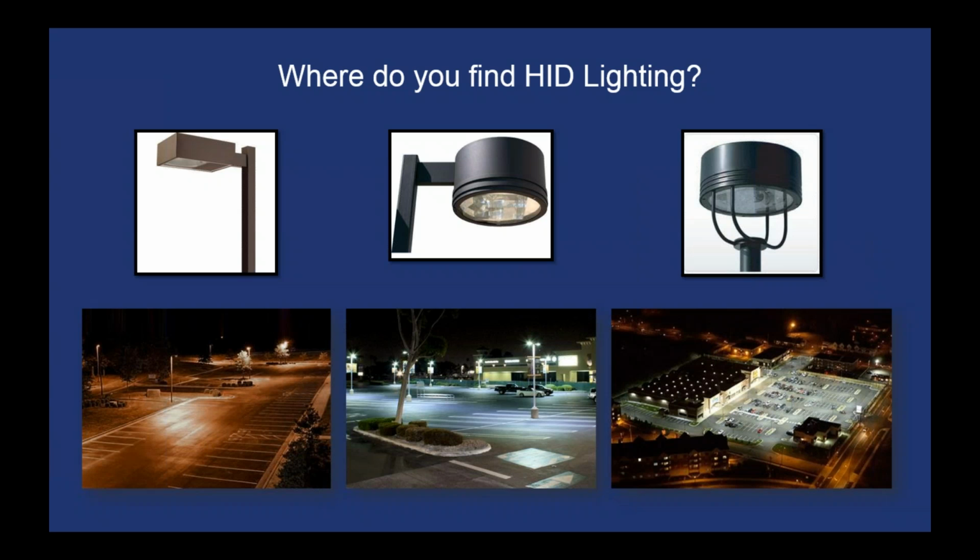With a glass lens on it, if you look up, you can typically see if it's tubular or bulbous, and identify that type of lighting. The height of the pole will often tell us what it is, and if we have a picture, we can probably tell just by looking at it where it goes. That's a whole other webinar, and we'll get into that. But this is where you typically find metal halide and high pressure sodium lighting in that type of place.